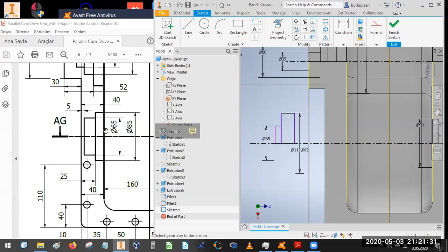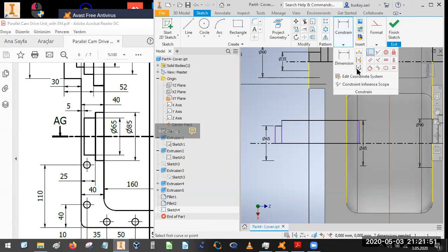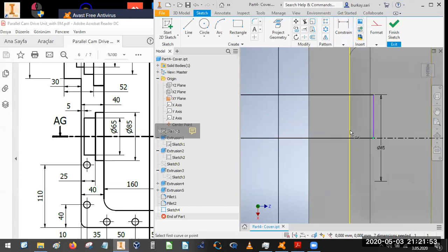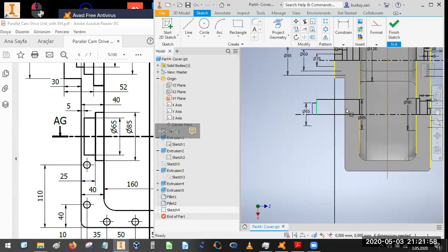And I would like to just go from inside to outside this time. From this point, we have 25. I will just move it to inside. And I would like to have this point on this line, have the coincident constraint. This point on this line. Okay. Next, I will just stretch it. We have also wall thickness 5 millimeter on inside, which I have seen at this point.